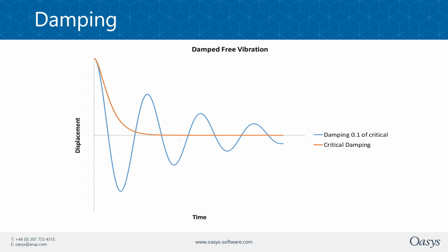Now, if this resonance was unchecked, the induced vibrations would eventually destroy the structure, a bit like Tacoma Narrows. But thankfully, structures have imperfections in them that can absorb the vibration energy, and we call this damping. You often hear the expression critical damping in vibration engineering. This is the level of damping where the structure returns to its original position in the minimum time after the movement. More damping than this slows the return to the starting point. More usually, less damping means the structure can overshoot and thus oscillate.